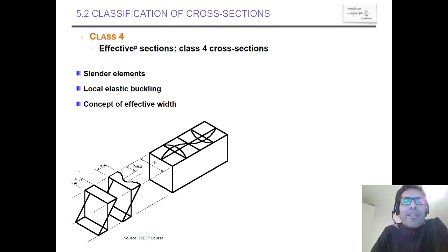Okay, so with that, what we are saying is that any element that is subjected to, let's say, bending or compression follows the regular theory of bending, in which we know that the strain plane epsilon is related to how the plane sections remain plane after deformation.